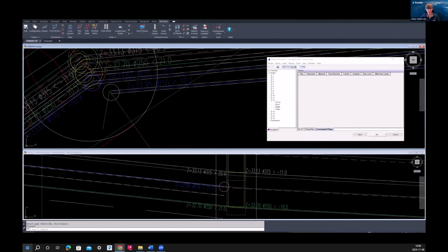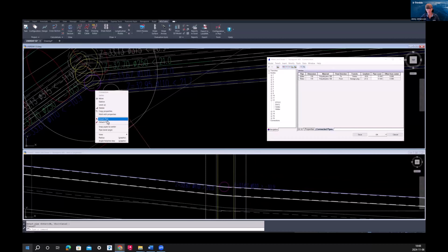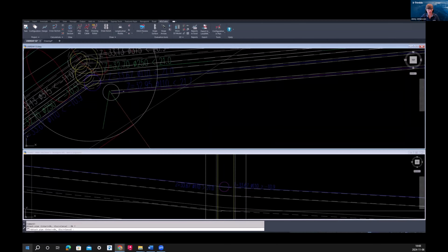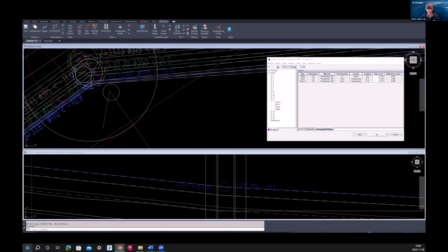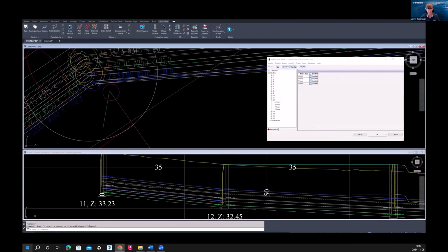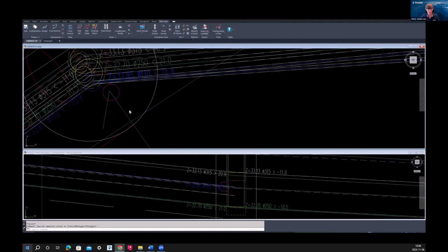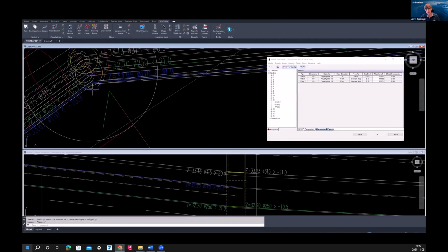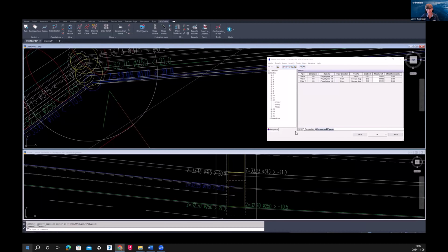Then we can right-click the other connection and attach the pipe to that one instead. We will see that the pipe is attached to the already existing connection, and from here I can see that there are 3 pipes connected. Now it's okay to remove this connection that is no longer used. If we add pipes in this way, we need to do it for one trench section at a time.